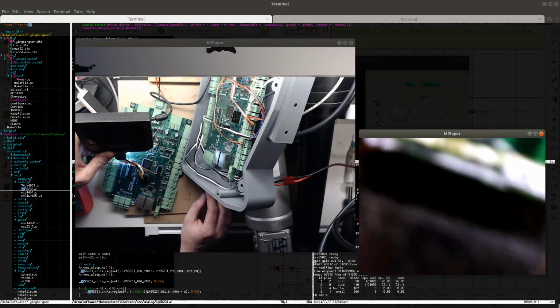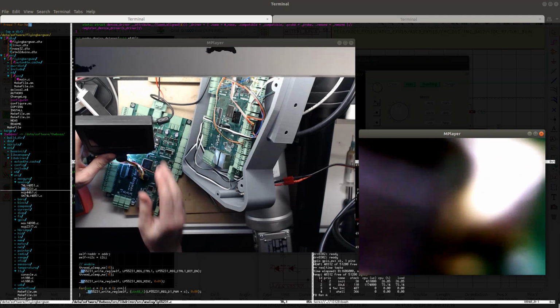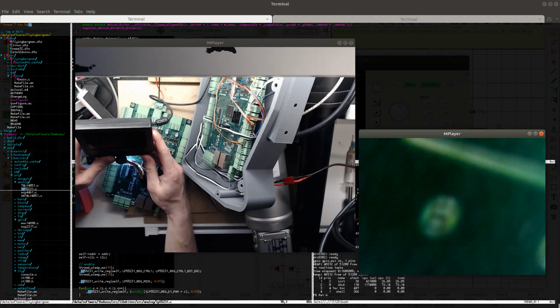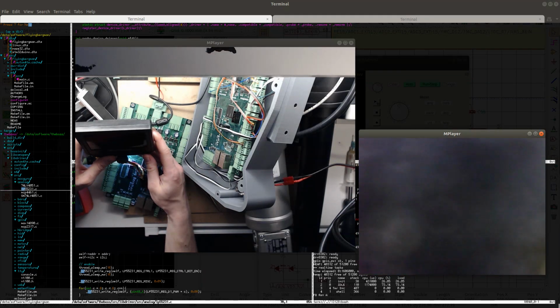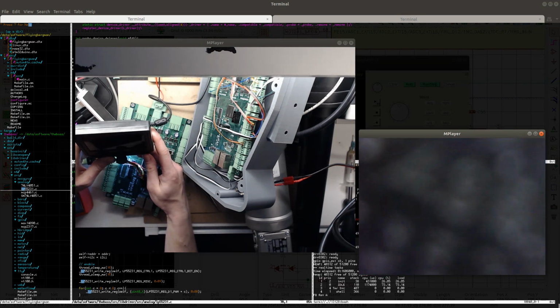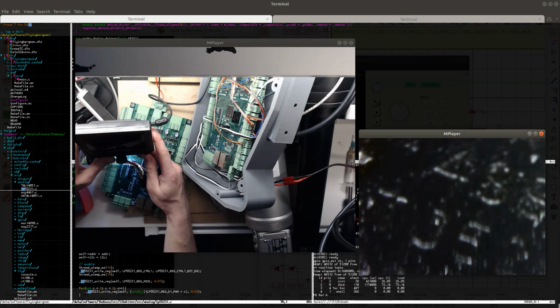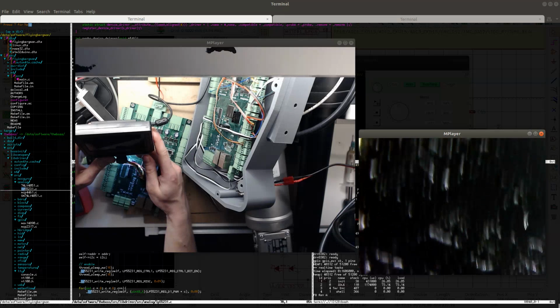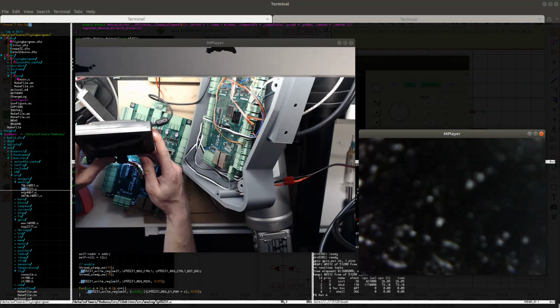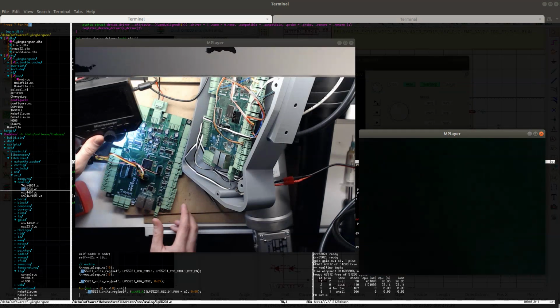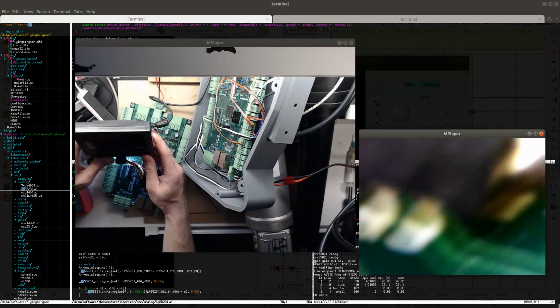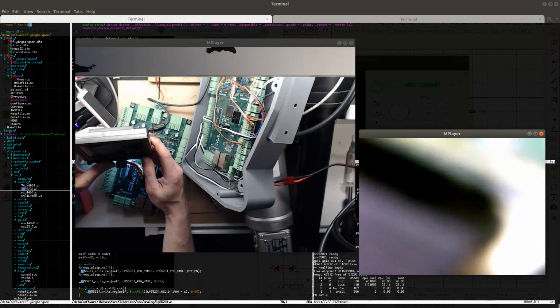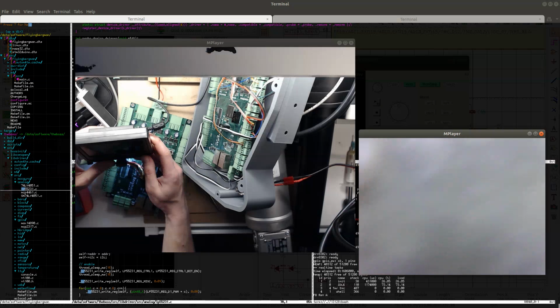Okay, so I find it hard to see whether the text is properly rotated. Because when the chip has flux on it, it's very hard to see the text. Okay. So the text is pointing that way. Let's see. Can we see where the pin marker is?